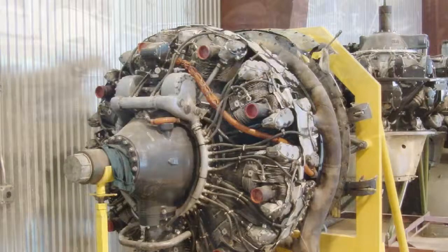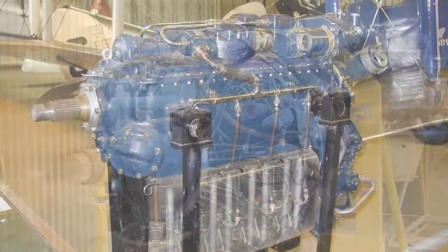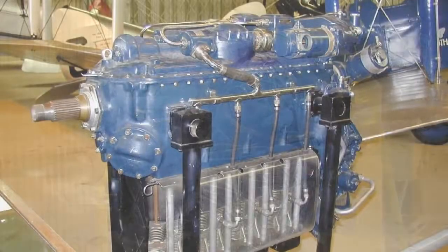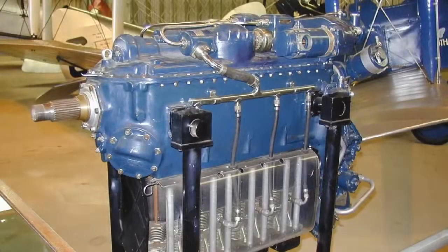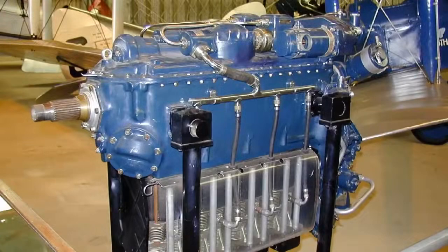We stated earlier that we could improve the power output of an engine and make it run more smoothly by increasing the number of cylinders incorporated into the engine. This is because the more cylinders there are, the greater the number of power strokes in 720 degrees of crankshaft rotation. The greater the number of cylinders, the smaller is the interval between power strokes. This interval is called the firing interval. 4 cylinders are generally regarded as the minimum number to give reasonable firing interval.